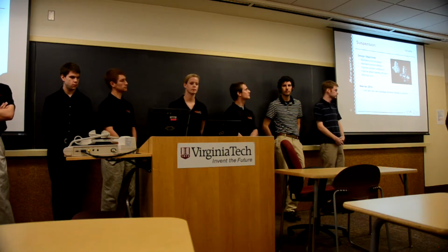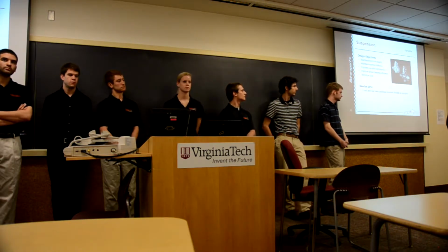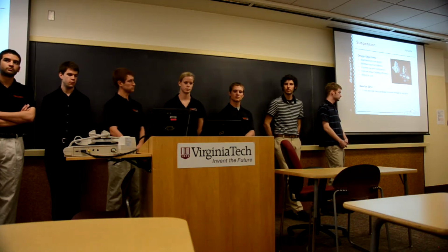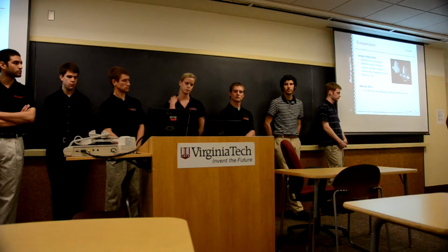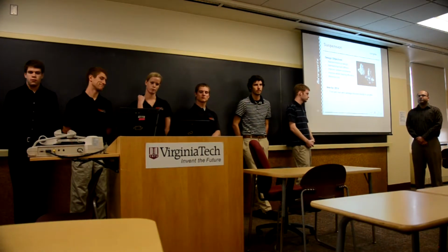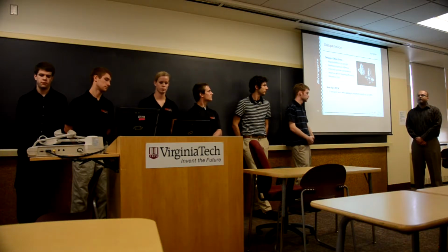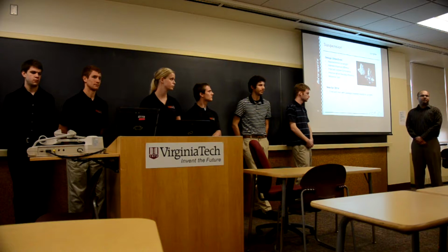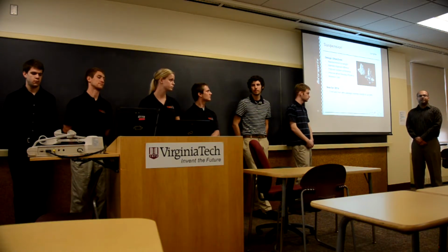Okay, for uprights, our design goals are basically the same. Keep the weight low, cost low, and improve stiffness, camber compliance, and bearing efficiency. One main new thing for 2014 is we're going to try to put the aero loads directly onto the uprights. That's going to affect the design majorly. We're going to have extra mounting points, and that'll affect size and weight.